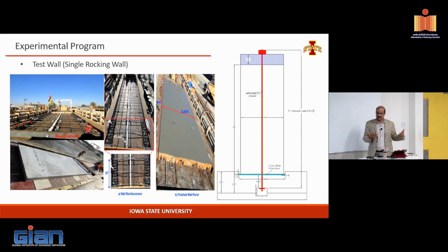There's no reason that we believe we need to have more reinforcement. We did put some confinement reinforcement in the corners, so that's the only additional steel that was put in. You could see, because that's a region that basically gets impacted during the rocking. So we can calculate what the contact is as it reaches a certain displacement, and that region was designed with confinement because when you rock, obviously you're going to get pretty high forces into that rocking toe, and I wanted to make sure that we provide adequate reinforcement.